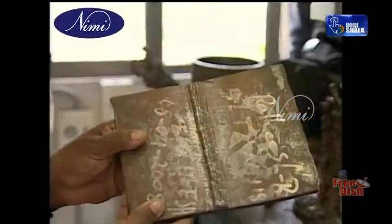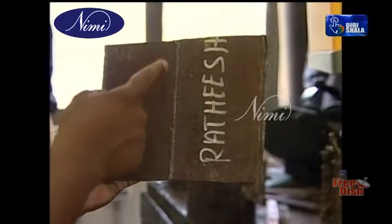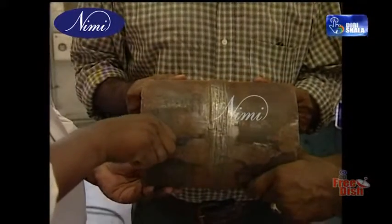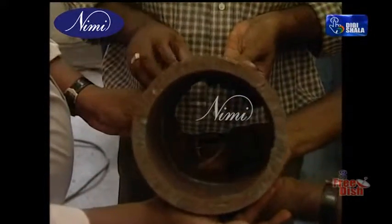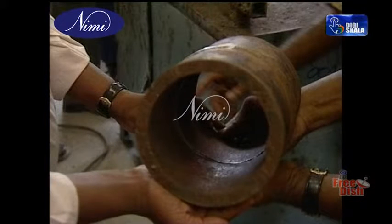Weld inspection. The complete weld shall be subjected to visual inspection to ensure uniform and correct reinforcement, and to ensure that the weld face is free from welding defects like crack, porosity, lack of fusion, slag inclusion, unfilled crater, undercuts, overlap, concavity, etc. Shall we learn in detail about these welding defects?